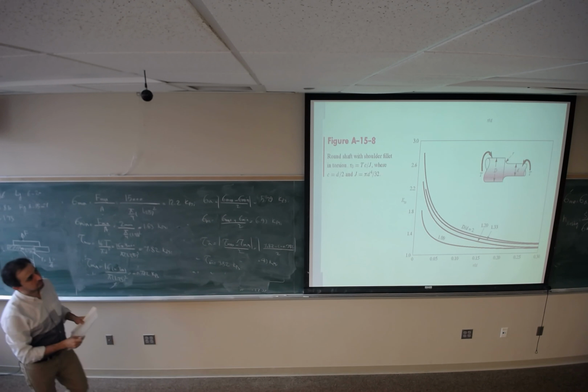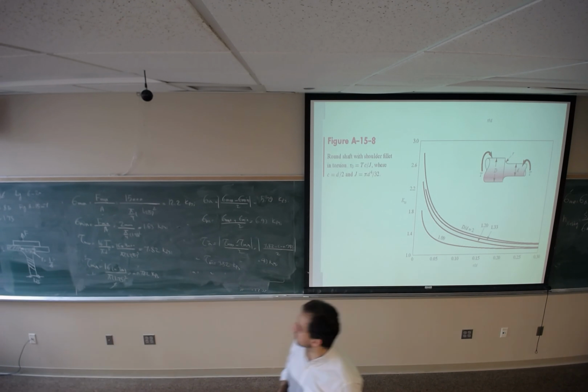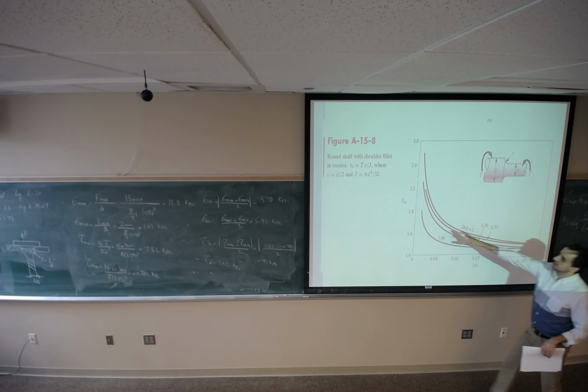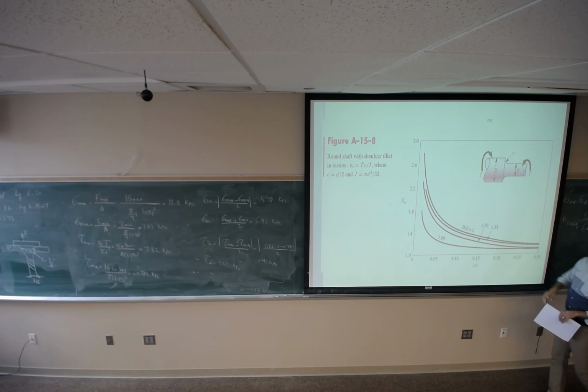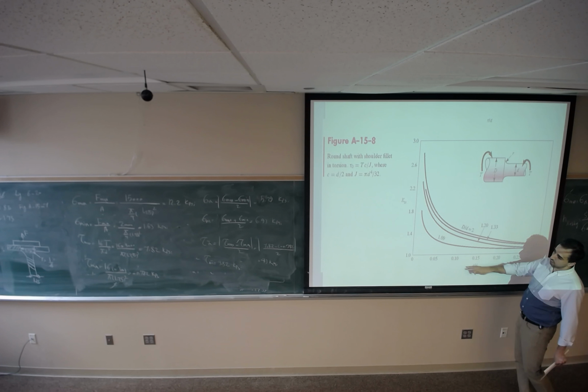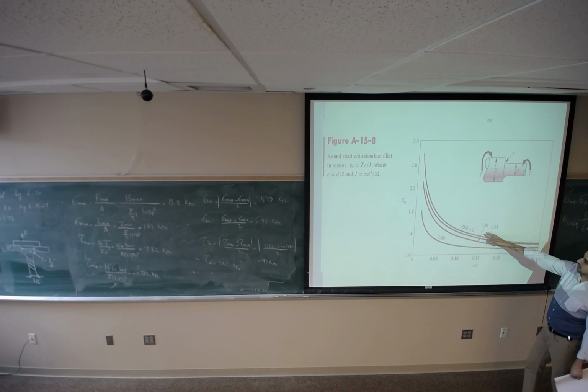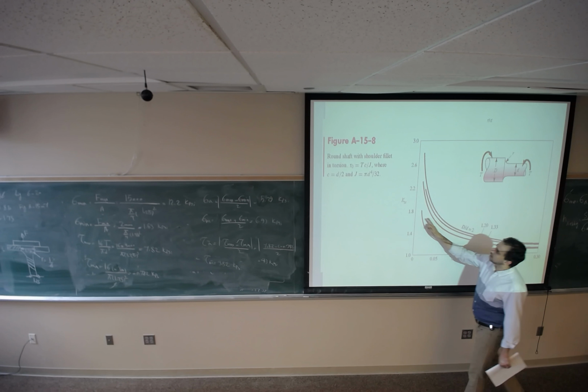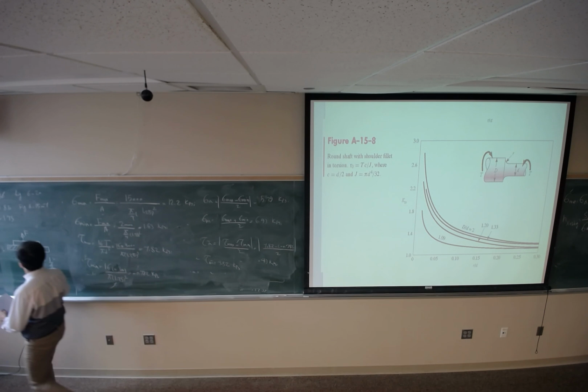See, the shear stress is coming from the torque or torsion. Find that figure which is going to give you Kts for the shear stress. We have the circular cross section with a different diameter, which is under torque. Read r over d, you already calculated that for the first part. D over d has been calculated. So read Kts.